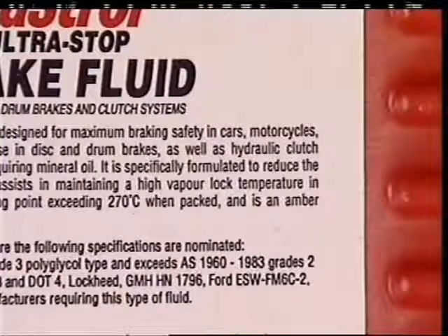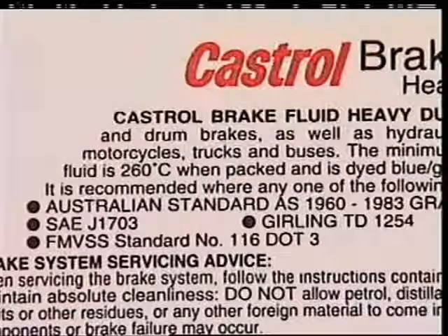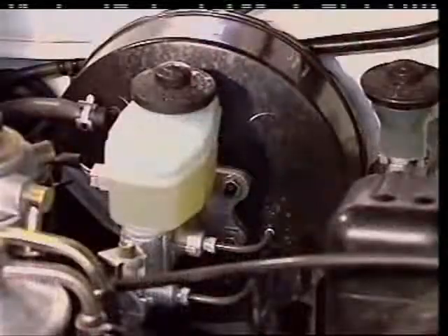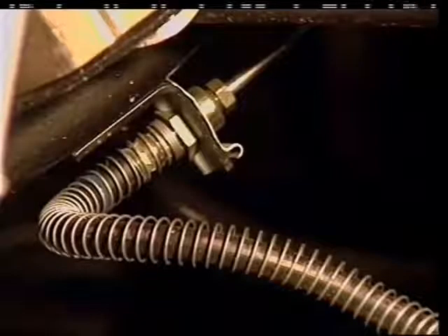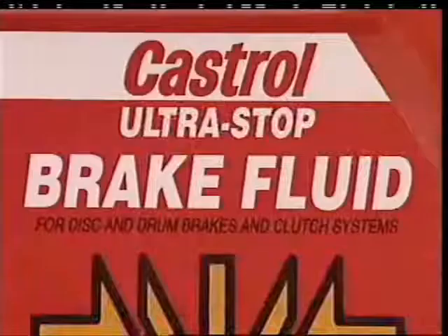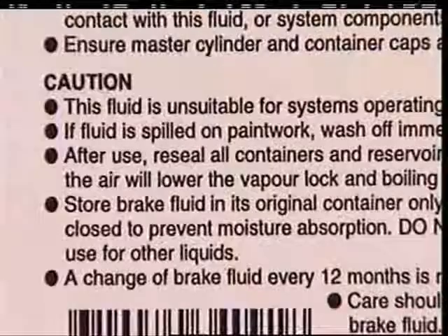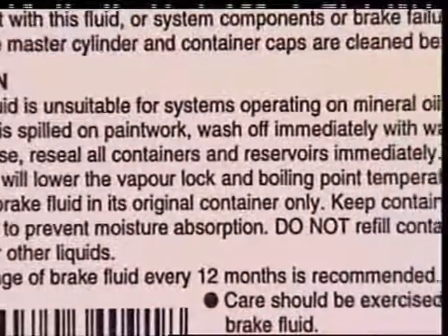It must have the correct viscosity for hot and cold conditions. Its boiling point must be higher than the temperature reached by the system. It must not damage seals, gaskets or hoses or cause corrosion. Glycol-based fluids meet most requirements, although they do damage paint. And they absorb moisture, hence the warnings.